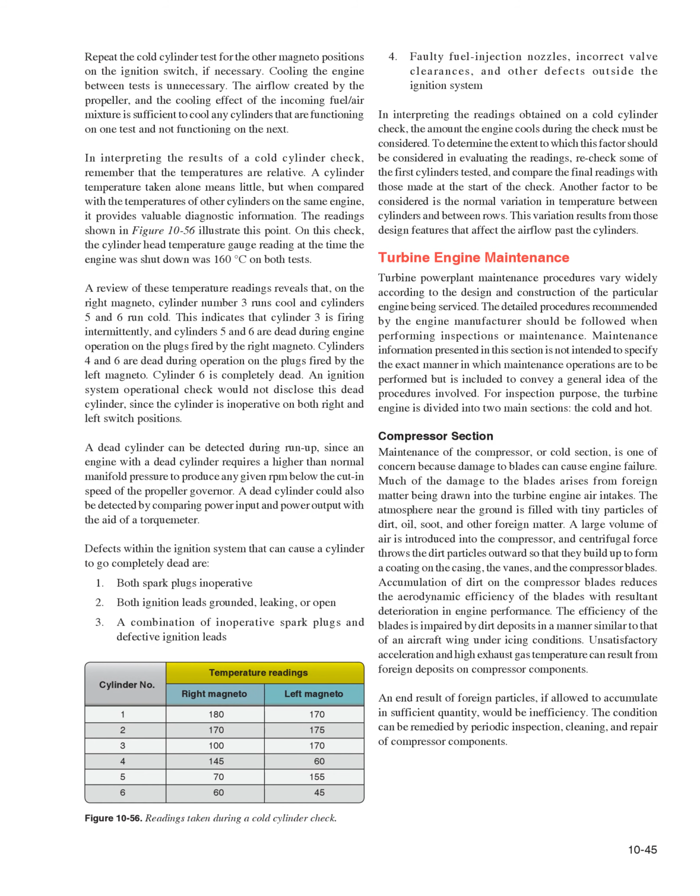Cooling the engine between tests is unnecessary. The airflow created by the propeller, and the cooling effect of the incoming fuel/air mixture is sufficient to cool any cylinders that are functioning on one test and not functioning on the next. In interpreting the results of a cold cylinder check, remember that the temperatures are relative. A cylinder temperature taken alone means little, but when compared with the temperatures of other cylinders on the same engine, it provides valuable diagnostic information. The readings shown in Figure 1056 illustrate this point.